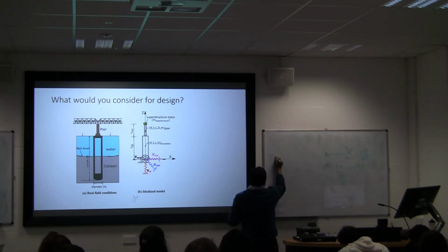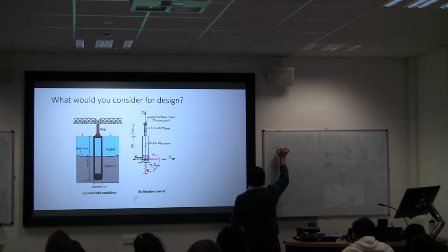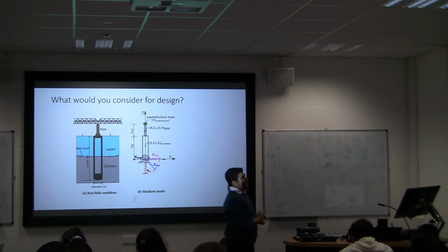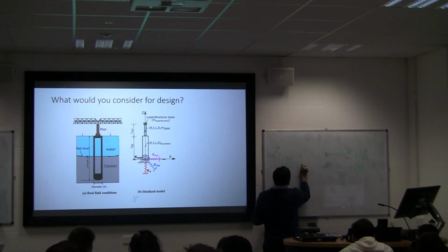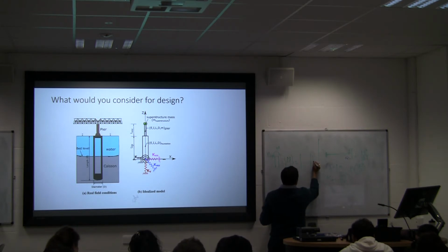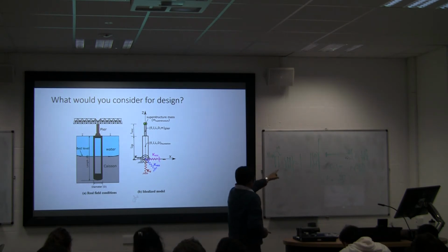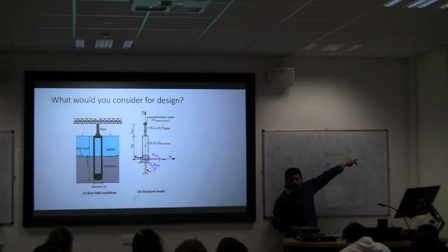Say that's the foundation, and the foundation has got a moment M and a lateral load H. You want to know what the rotation and deflection are, because a lateral load gives you both. If I apply a moment, it also gives me both.